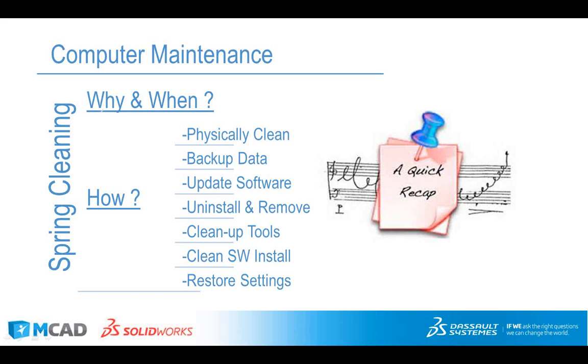Then run some cleanup tools. We looked at SolidWorks RX, how we can kick off some of those to get rid of the temp files. We looked at the Microsoft cleanup. Then we went through the SolidWorks clean install, how you're basically uninstalling all major versions of the software and add-ins. And you're getting rid of program data, program files, just all the extra stuff that is installed, all the data that's installed when you install the program. So we're basically trying to wipe that information off the system. Then reinstall it all straight from the fresh download.